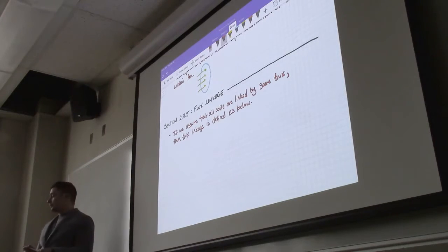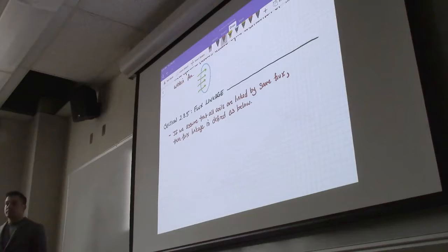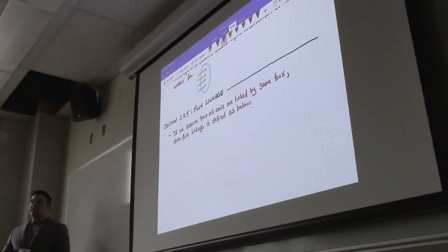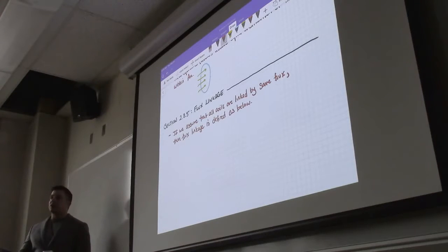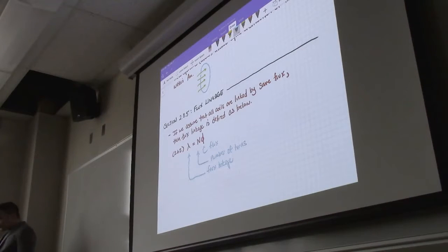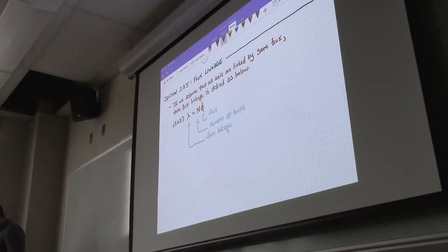Yes? So that means that they're all getting the same current, right? Yeah, that's one way of looking at it using the electric circuit analogy. That the current flowing through all of those coils is the same. Okay? Right, so our lambda is equal to the flux times the number of coils, again assuming that the coils are linked by the same flux.